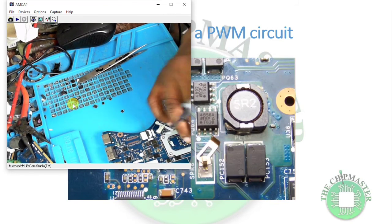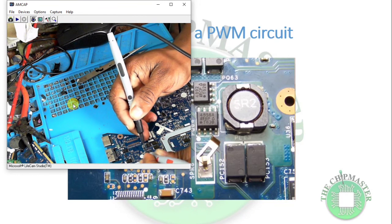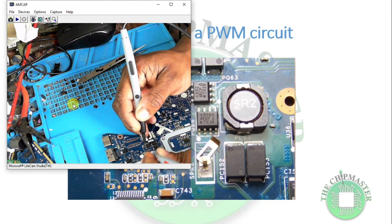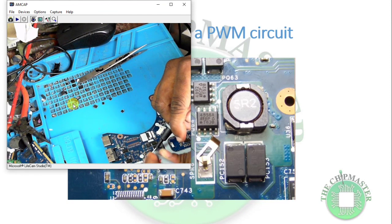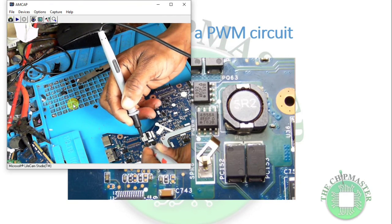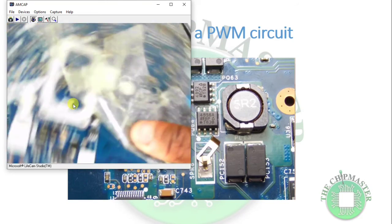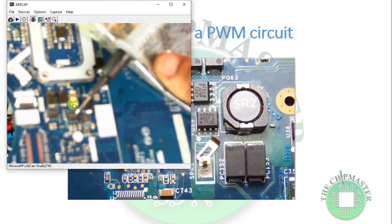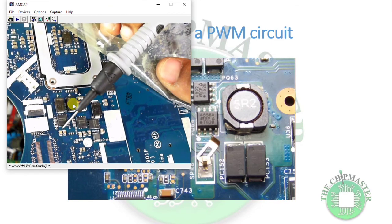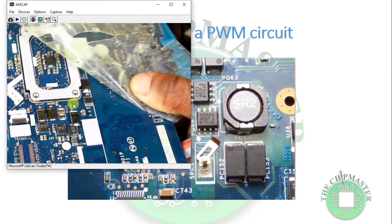here are some other MOSFETs, and these MOSFETs have the drain pin connected to a capacitor here, and this is their upper MOSFET. These are all their upper MOSFETs, see, all connected to the 19-volt rail. Alright, the drain pins are connected. So as you can see here, this is their upper MOSFET. This side is the drain, this is the drain, and it's connected to these capacitors. These are filter capacitors, which have the 19 volts.